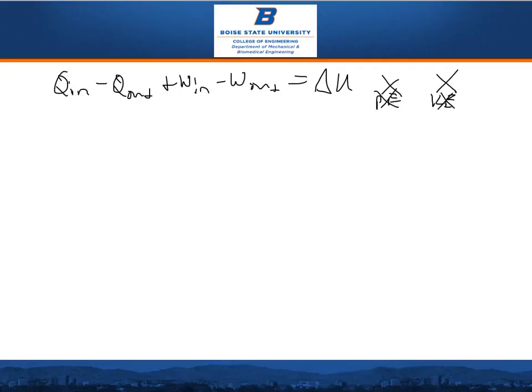Also remember that if it's expansion, the work is going out. If it's compression, the work is going in. So compressors are work storage devices, turbines are work delivery devices. Okay. The next subject is that the change in enthalpy for a constant pressure process, delta H, is equal to delta U plus the boundary work. So we can interchange that. That proves convenient frequently when we're trying to convert from internal energies to enthalpies, or vice versa, given the variables that we have to work with in our problem.